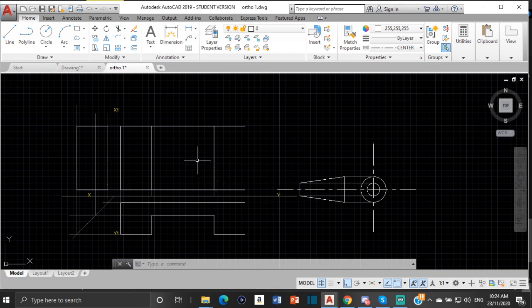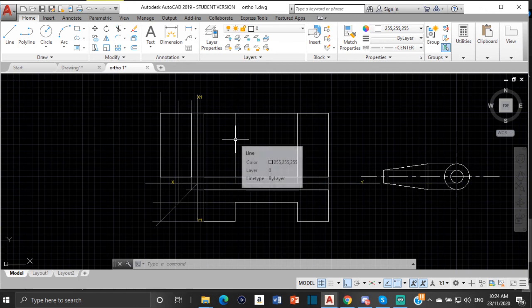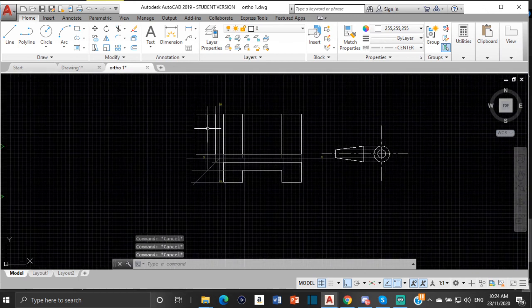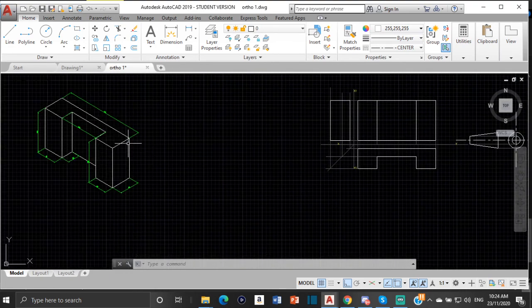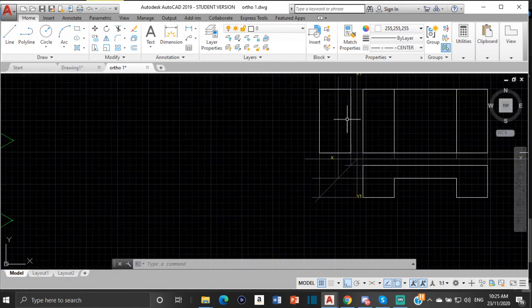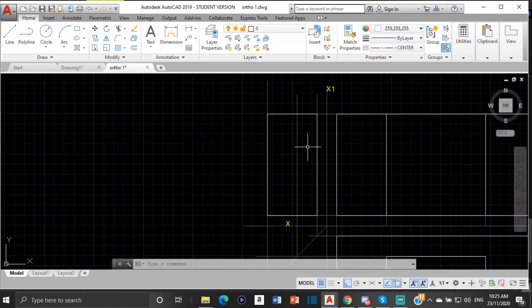All right. Oh, speaking of hidden details, I forgot one thing about this drawing. When you're looking from the side, here, you will have this thing here. So you have this line here. There'll also be a line right here that we're not seeing right now. Just like you have this line on this side, there's one over this side here, but we're not seeing it. And because we're not seeing it, we have to still represent that it's there, but we have to use a broken line.